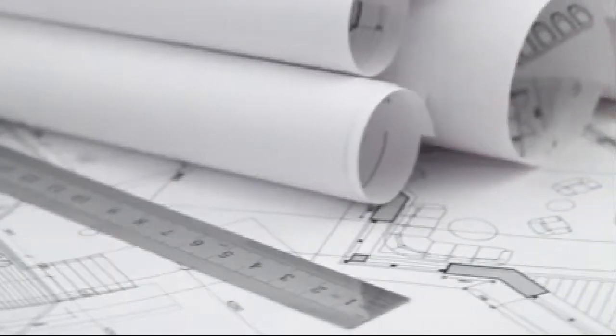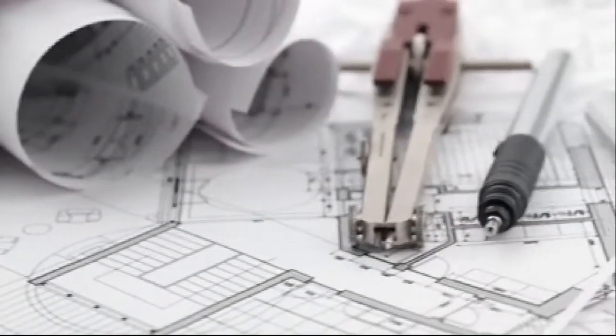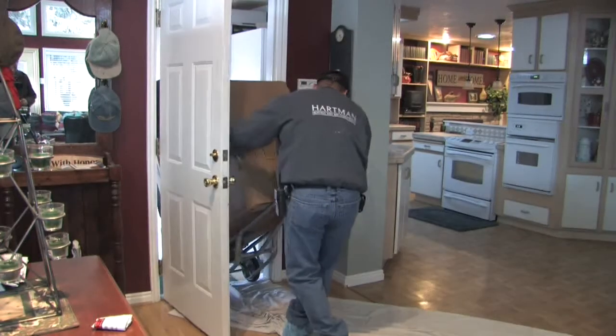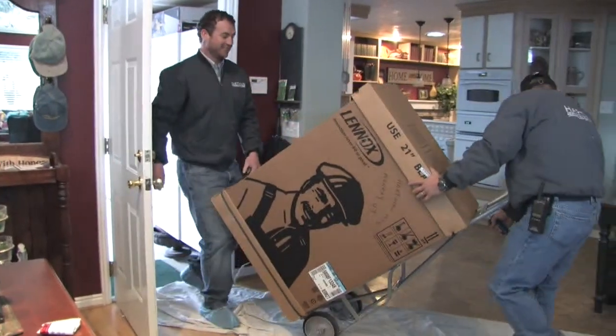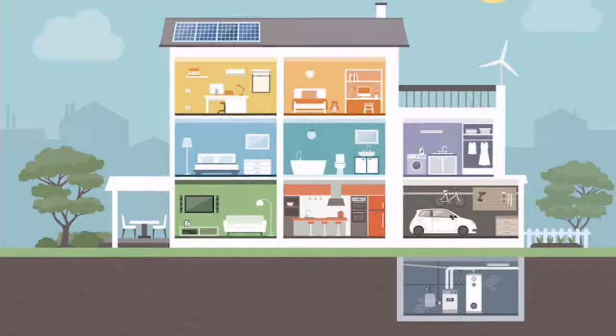There are many options when it comes to zoning, with some practical solutions and quite a few impractical ones. For example, adding multiple extra furnaces and AC units is usually not the answer to a simple zoning problem. A common two-zone system from a single piece of HVAC equipment is to place the master suite on its own zone and the rest of the home on another.